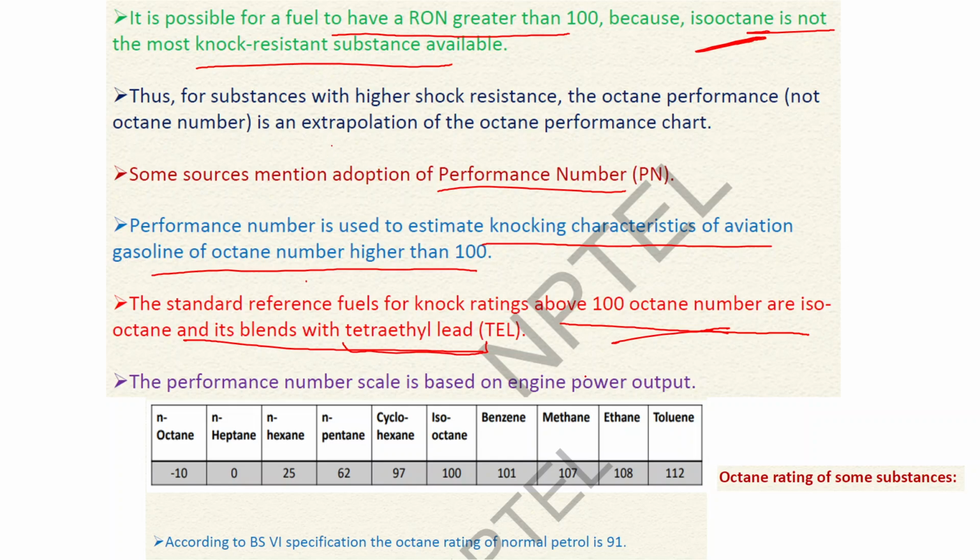This tetraethyl lead, on introduction to the gasoline, instantly forms free radicals, which again form free radicals with the gasoline as well as the oxygen present in the engine, thus preventing oxygen and fuel from instantly, rapidly reacting with each other and combusting. Okay, which therefore helps in resisting the knocking of the engine. Okay.